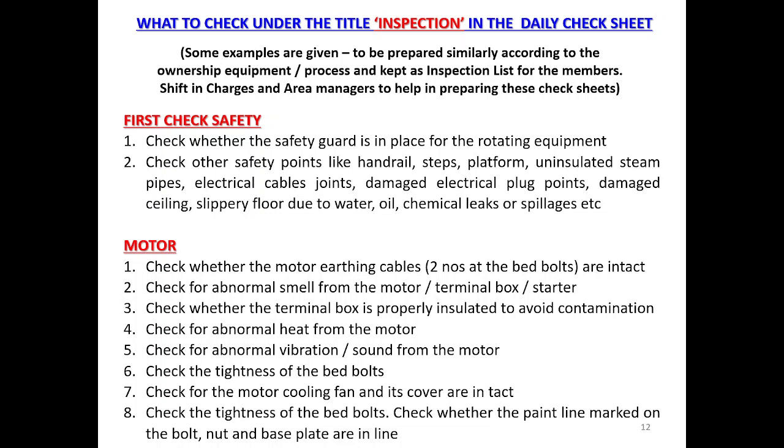Check for abnormal heat from the motor or starter. Check for abnormal vibration or sound from the motor. Check the tightness of bed bolts and ensure the black line marked on the yellow background is in a straight line on the nut, bolt and base of the equipment. Check that the motor cooling fan and its cover are intact.